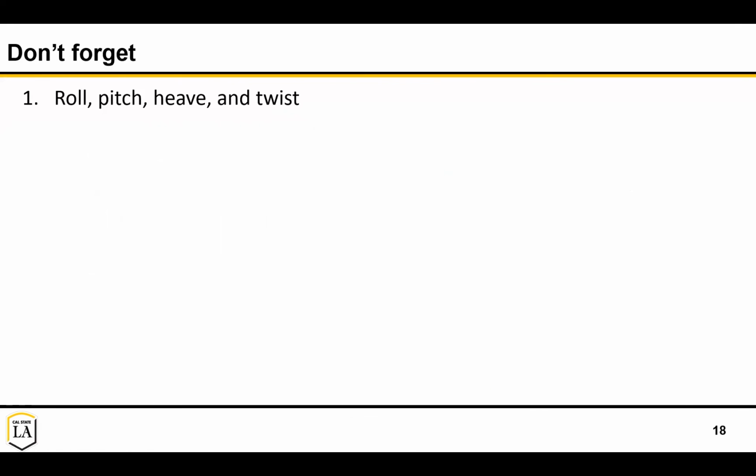There's plenty of things I haven't discussed here, which are some things to remember, is that you have this motion in roll, which we talked about, and we talked about some heave motion, but you also have pitch and single tire upsets or twist, also known as warp, that you will want to take into account. Might check into those frequencies and what's the max travels, and is that acceptable? And keep in mind, you even see a few of the top teams these days, even including a third element spring, a heave spring to control just the heave motion.